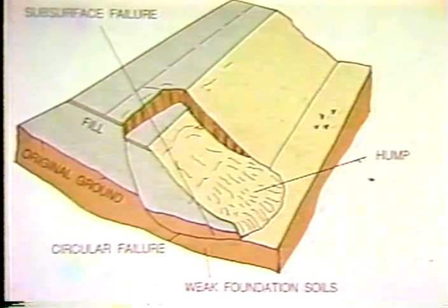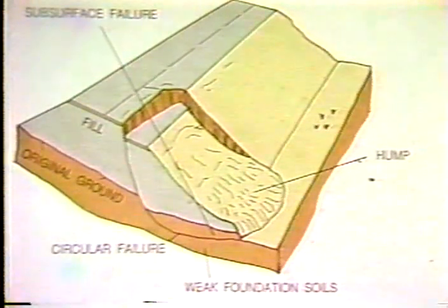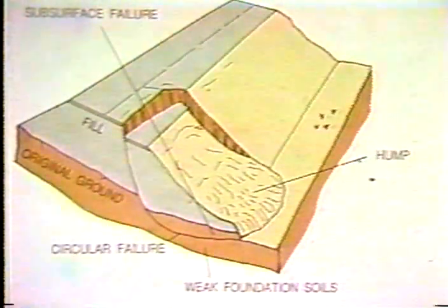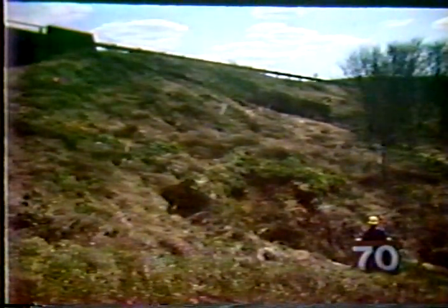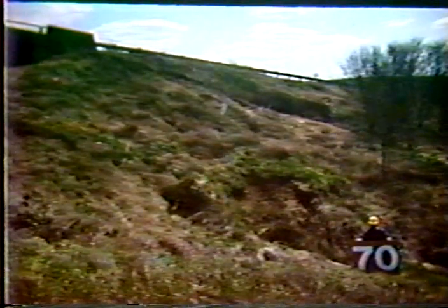Another application where a berm would be used, note that there's a very deep failure. The bulge at the toe goes way beyond the original toe of the slope. We can get a mass of material at the toe there by extending it and building a berm. A situation where a berm might be used, shown in this failure at a bridge approach.